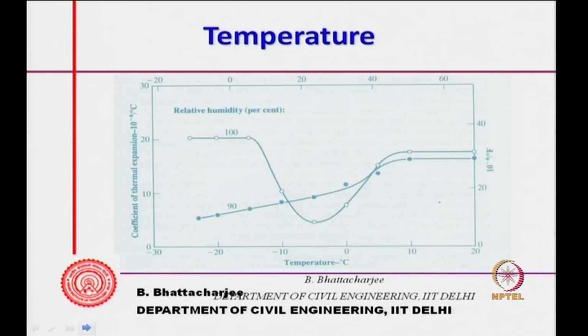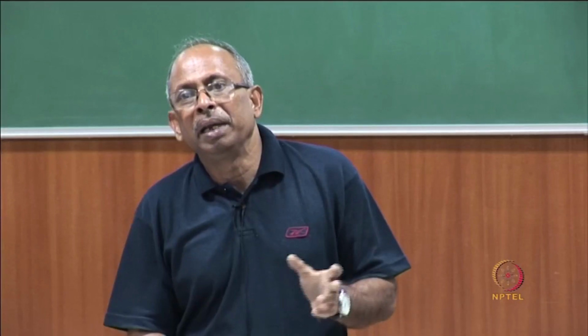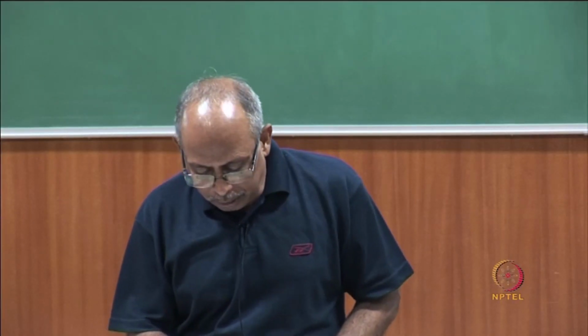There are some observed experimental results. At relative humidity 100%, the coefficient of expansion is something of this kind, and of course, it depends on temperature, down to -20 at low temperature. Now, water will be more or less mobile in this, although the properties of gel water are different. It is not the same as free water. It will not be like free water getting frozen. This may not get frozen at all, but the properties are different.